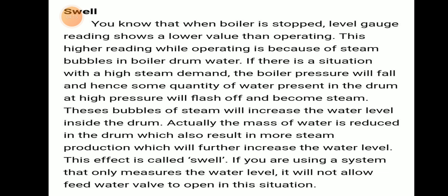This bubble of steam will increase the water level in the boiler drum, but actually the mass of water is reduced here. The bubbles just make the water level appear to increase in the drum. After some time they will come down, but the mass of water has actually reduced, which also results in more steam production. This increase in water level is known as swell.